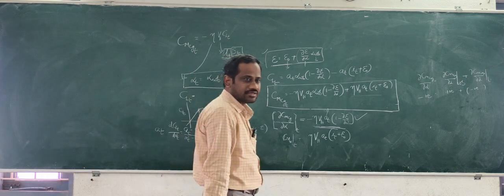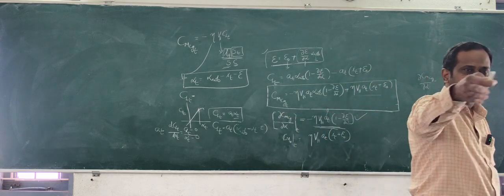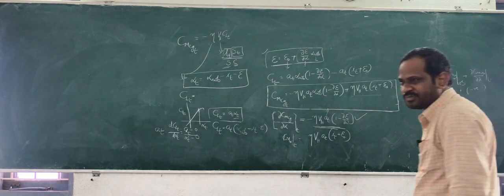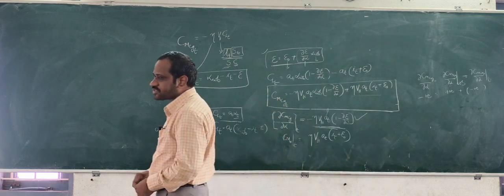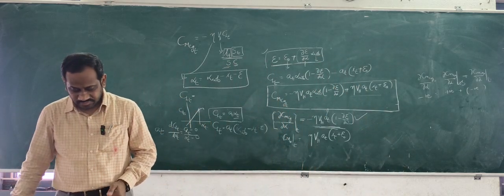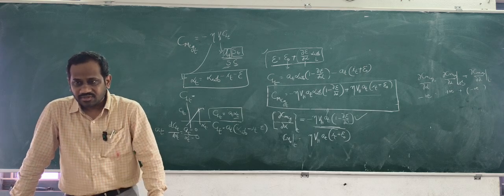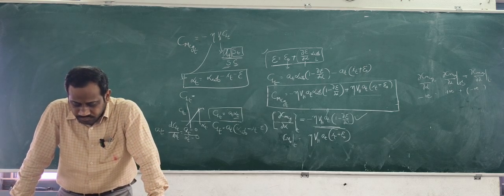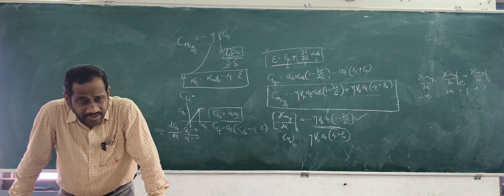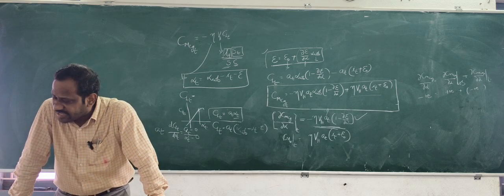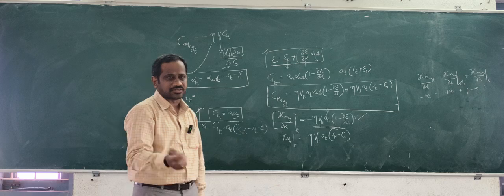The name of LT is tail moment arm, the location of the tail with respect to the center of gravity in the downstream direction, or by increasing the tail surface area, or by increasing the slope of the lift curve of the tail AT. Anything you have to increase